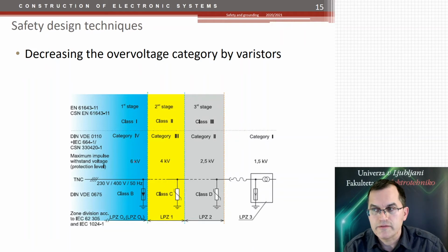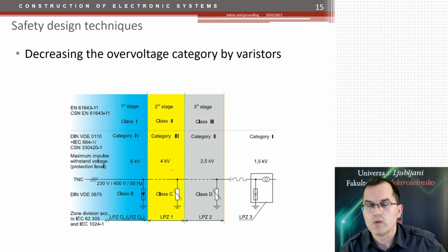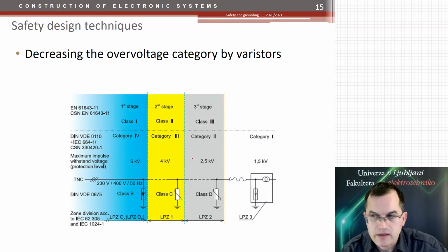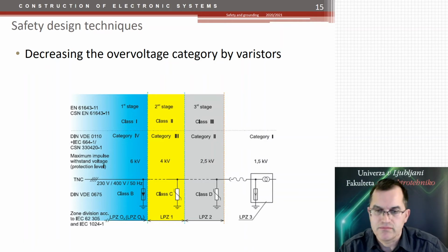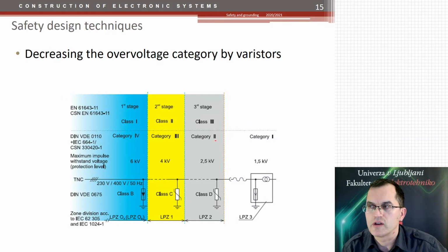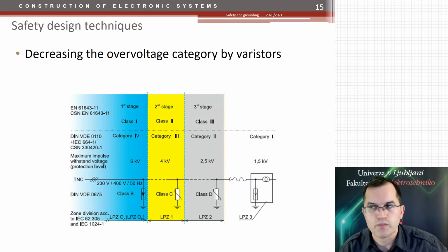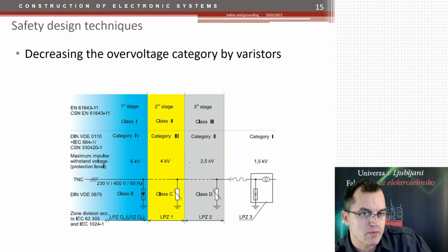And therefore, for example, if you're making a device that would be used inside the house, plugged in a socket, such as any 230 volt device that you plug in your socket within your house, you would have to classify it for category 2. And it would have to withstand 2.5 kilovolts between the high voltage part and the parts you can touch.